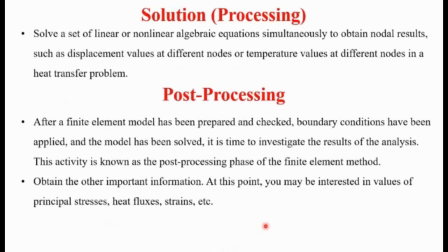Then next, the second phase is the solution phase, or sometimes it is called the processing phase as well. In this phase, we solve a set of linear and non-linear algebraic equations simultaneously to obtain nodal results, such as the displacement values at different nodes or temperature values at different nodes in a heat transfer problem. In case of solid mechanics problems, we have to calculate the displacement, stress, strain values.